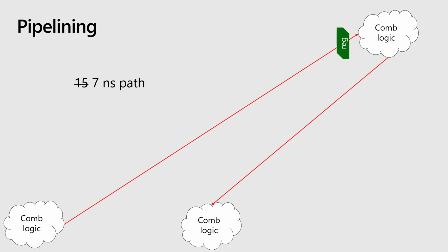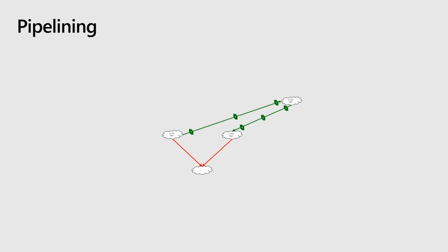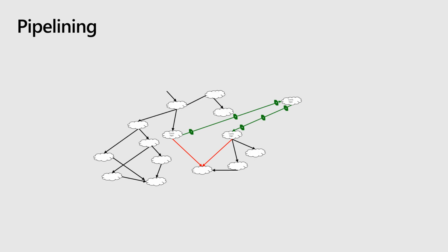You insert a register, and you insert another register here. It's only 1 nanosecond because, again, the combinational logic delay is really not that much. So you insert another 2 registers, and then another 2, and 500 megahertz. That's great. But you broke the design functionally because you didn't consider all the other paths in the design, which relied on that precise cycle-based timing. And then this could cascade out to the rest of your design.